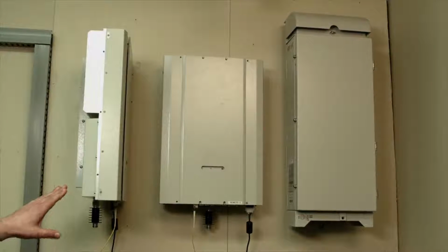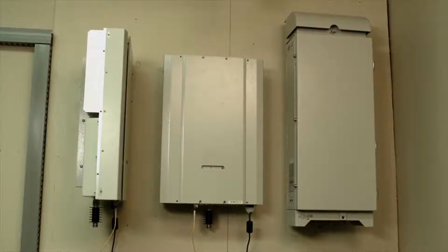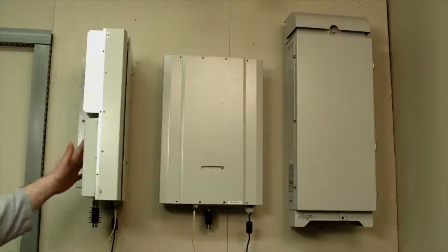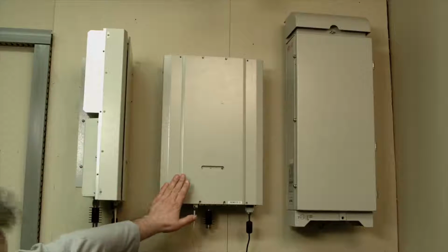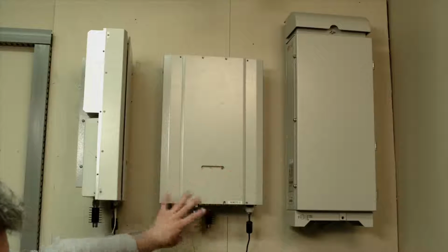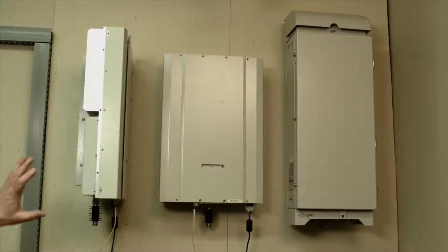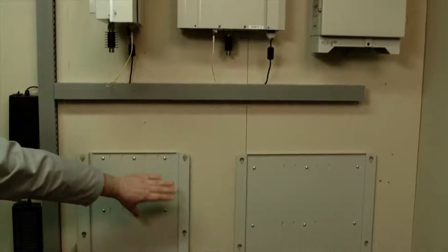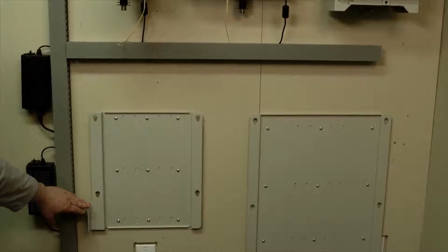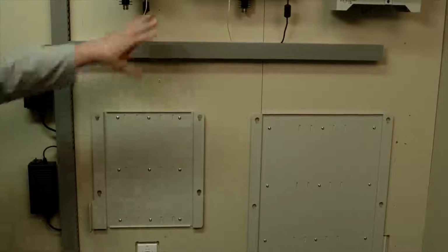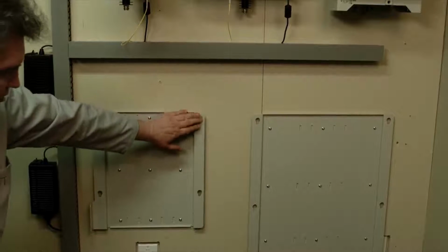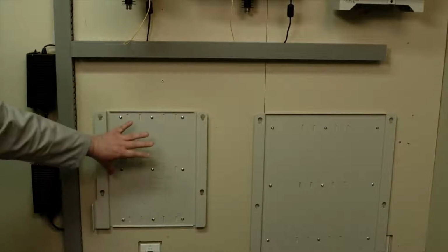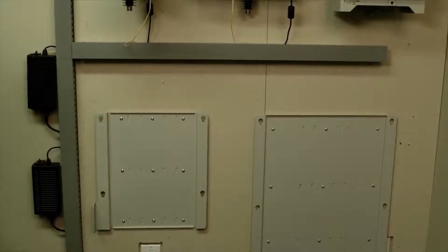The T30 unit can be installed on the wall sideways as shown here, or on the back as shown in this section here. The installation is done by assembling first the mounting plate on the wall and then hanging the unit so it latches in the openings available in assembly plate.